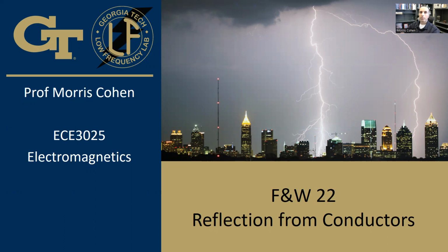But in order for radio waves to be interesting, we have to have them interact with something else, with some material, some object. For example, in order for an antenna to receive a radio wave, the radio wave has to strike an antenna. That antenna could well be, for example, a metal wire. And when the electric field strikes this metal wire, it's going to induce currents to flow along that wire, and that's what we can sense with some electronics. So that's one way in which a radio wave can interact with some object in order to produce a response.